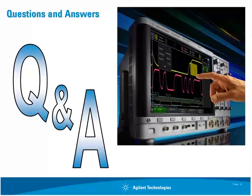Noise, if it's random, if it's Gaussian, which is typical white noise, will have extremes that happen more infrequently. They'll have extremes of positive peak noise and negative peak noise that happen less frequently than the 1 sigma type noise. If a scope has a fast waveform update rate, it's going to pick up those extremes extremely fast, whereas a scope with a slow update rate is not going to show you those extremes.